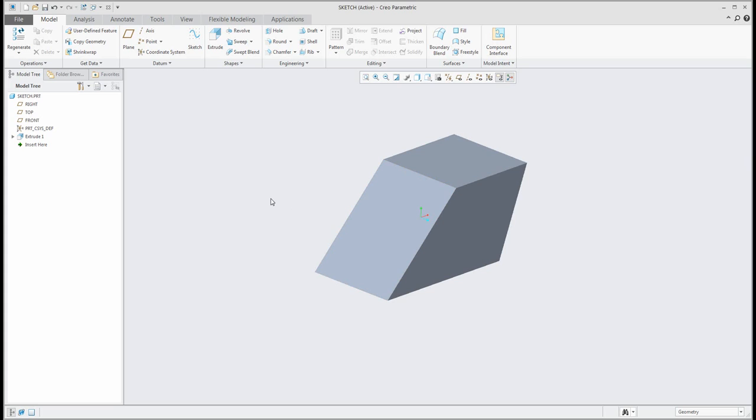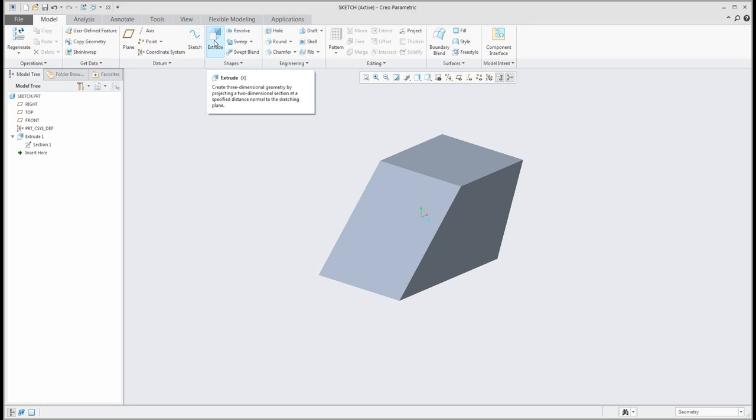If you are working with 3D models, many times you have to specify, for example, the extrude feature, revolve feature, or another type of feature, and inside of this feature it is necessary to define the section. Or you can select the sketch feature and directly create 2D curves. I'd like to focus on the sketch functions, and for better explanation I will create another extrude feature.